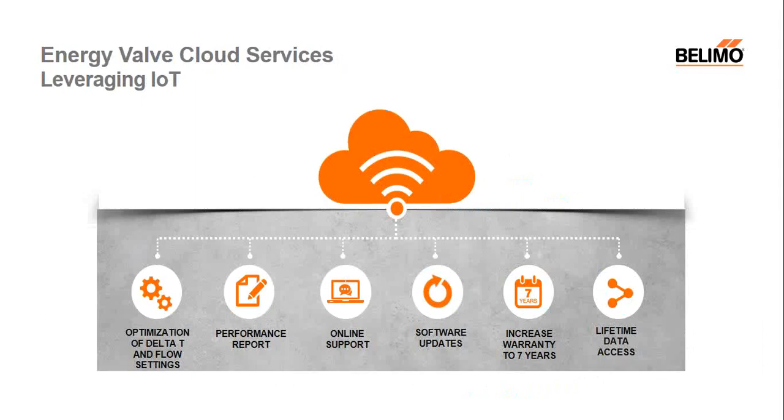These valves could be up on the roof, up in the ceiling, down in mechanical rooms, behind cabinets. So it takes a lot of time, just one, tracking those down, and two, updating those. Connected to the cloud, all the updates are automatically pushed directly to the valve with the push of a button. Those updates can also be reviewed before loading, similar to what happens on your cell phone or your computer, where you can view those prior to loading.